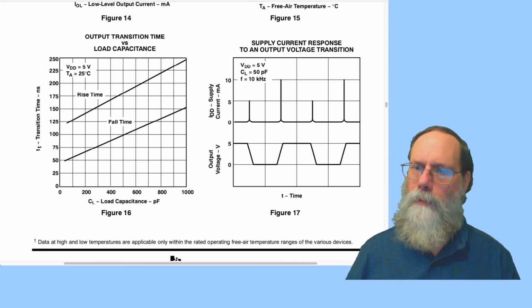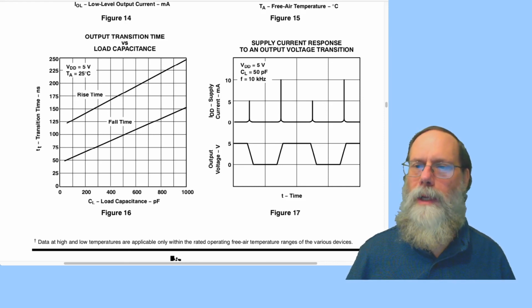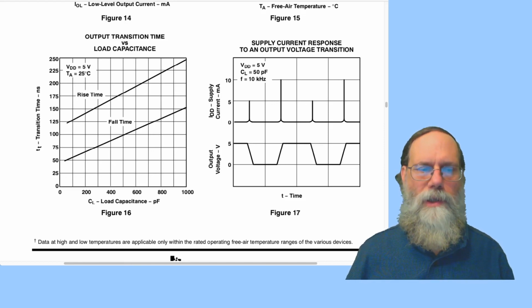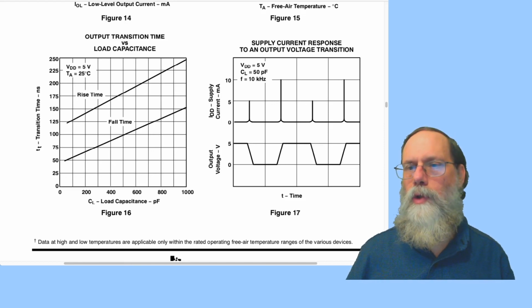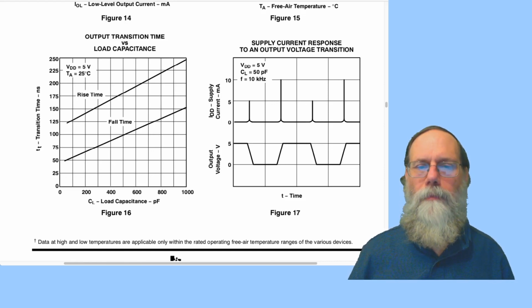You only have current to the bottom power rail and no current to the top one. That has to be provided externally for the open collector or open drain comparators. We won't be using those in this course, but there's a discussion of them in section 33.2 of the book if you do have an application that needs them. And I think that's it for comparators.